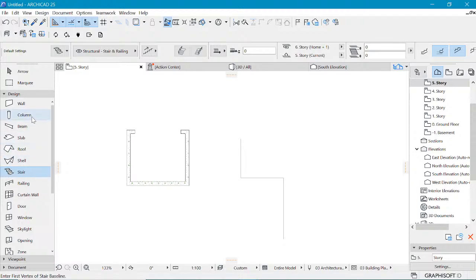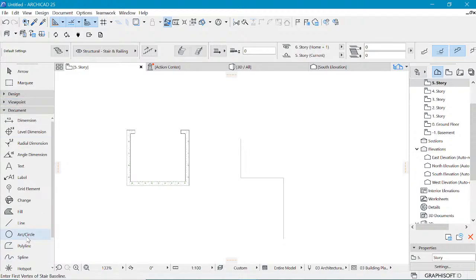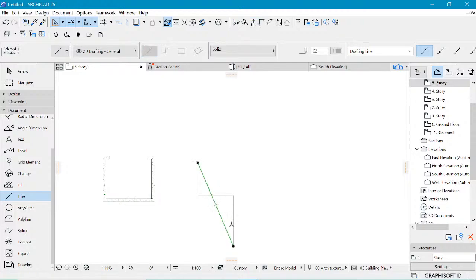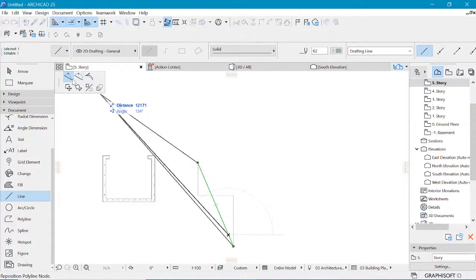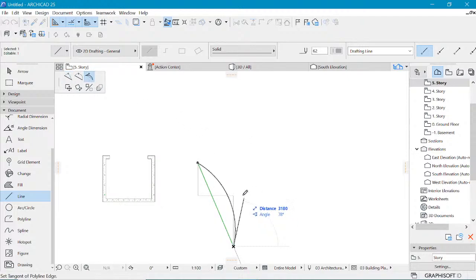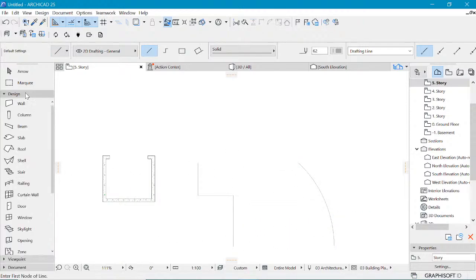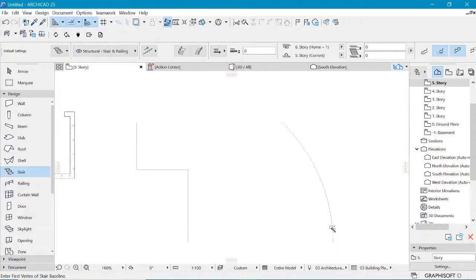If you have ideas such as a rounded kind of thing, let's say you wanted your stair to run from here to here but in a circular motion, let's use a curve now. Let's say we want to use this like so and move this across here. You can pick a staircase and space click, just hold down the space bar, and there you have it. Isn't this pretty cool? You can have a stair which follows that profile.